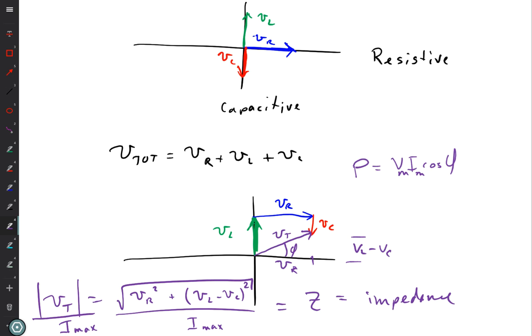And so to make it so your refrigerator doesn't cost you as much to do the same amount of cooling, you would want to put something like a capacitor in parallel with it to bring the phase angle closer to 0 when it turns on. The capacitor in parallel doesn't use any energy, doesn't give back any energy, but it makes it so it doesn't look like you're using as much, even though you're using the same amount.